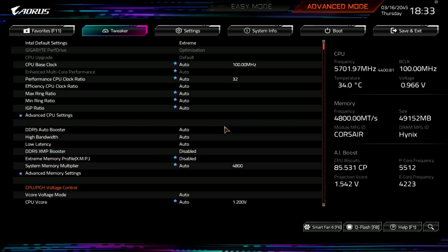It does, funnily enough, significantly reduce the peak voltages, because the way the V-droop compensation works is that it just slaps the maximum theoretical current that the CPU can pull multiplied by the AC load line onto a vid request. So if you set the AC load line really low, your peak vid requests are going to get a lot lower, but your full load performance is not really going to change too much.